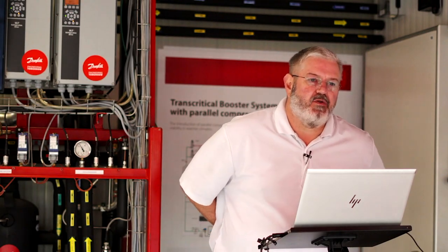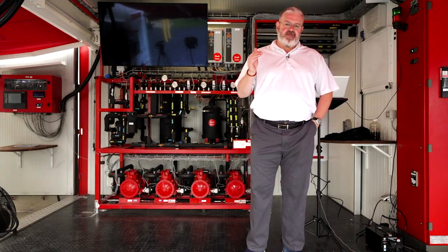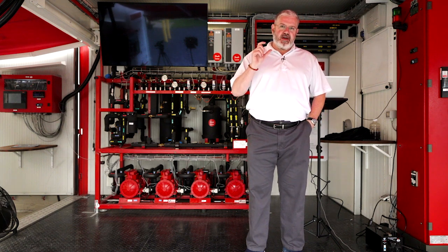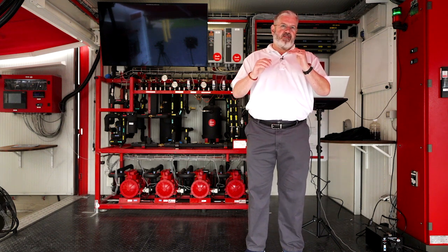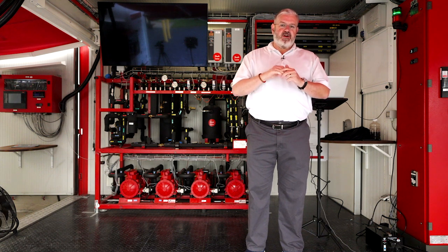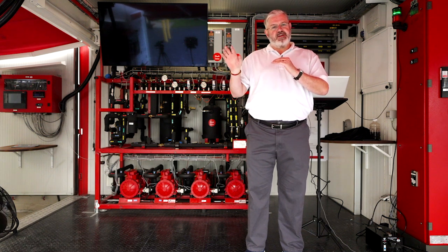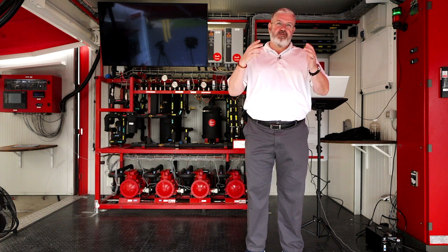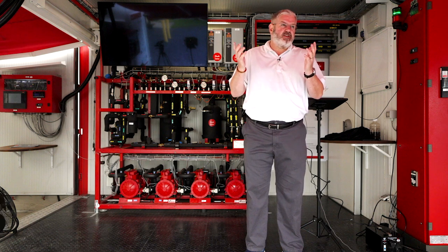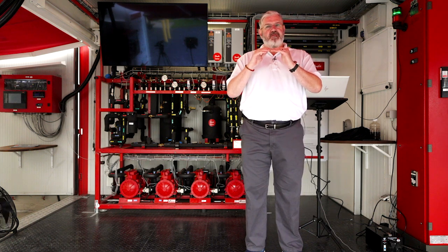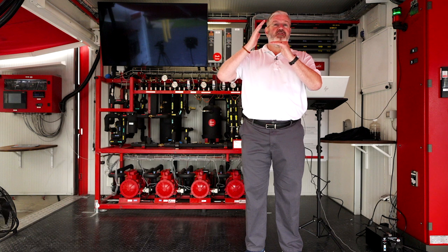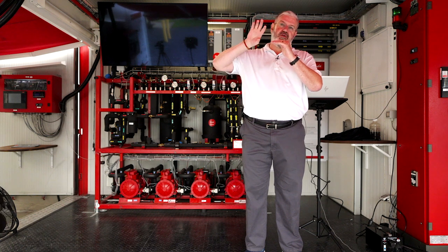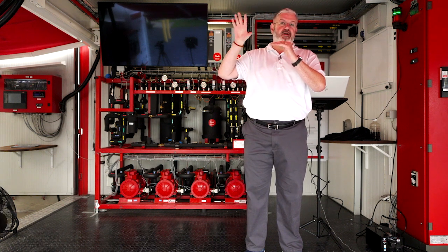So we have a question: how would a CO2 system work in sub-zero ambient temperatures? I got that one yesterday. It's a really good question. If you think back to when we talked about the high pressure valve, you give it a minimum range and a maximum range. So regardless of what temperatures the gas cooler is seeing, if you tell it the minimum is 600 pounds, whatever temperature that equates to, let's say that's 50 degrees-ish. If you set that as the minimum, it's going to close itself off to build the pressure in the gas cooler to not be above your minimum setting.